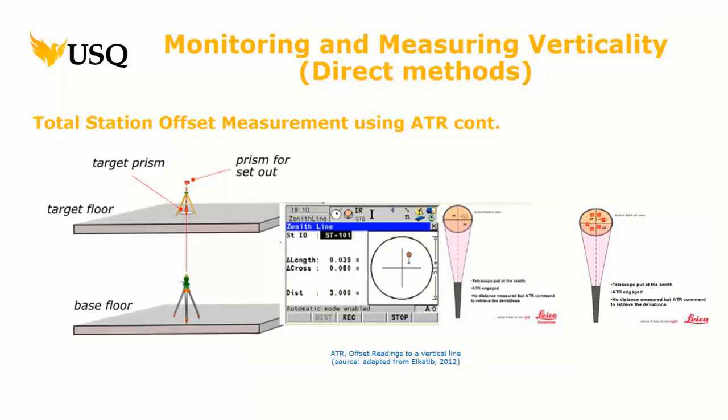Now, to do this properly, you should actually go back to your SVY 2301. There's a description there of ATR, automatic target recognition, and how it works. I didn't repeat it because I presume you'd love to go back and reread that stuff. But basically, there's a falsehood some people, even surveyors, think, that the automatic target recognition is the instrument moves onto the target precisely.